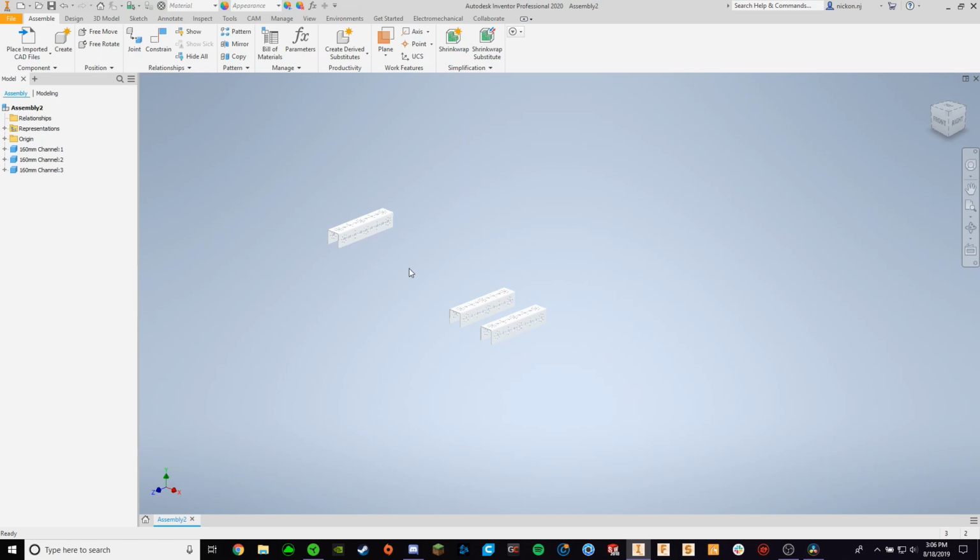You can copy and paste a lot of different things in Inventor. Paste some more, so you've got 4 Tetrix channels total. If you take your mouse and click and hold on a channel, you can actually drag it around. So if a part is in your way, you can move it around by dragging it out of the way. Later on, with this little dragging motion, you can make wheels sort of turn or other parts move, depending on how they're constrained. So now, let's take a look at how we can put these parts together.